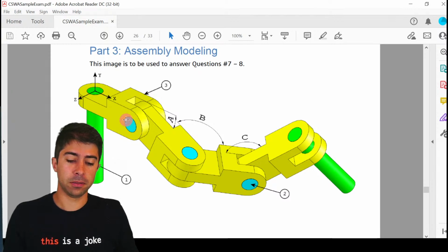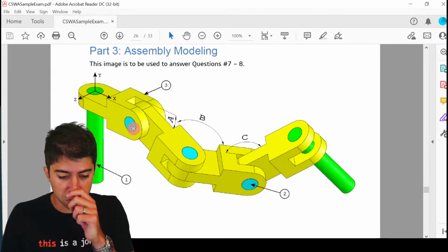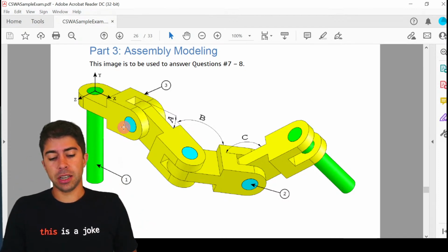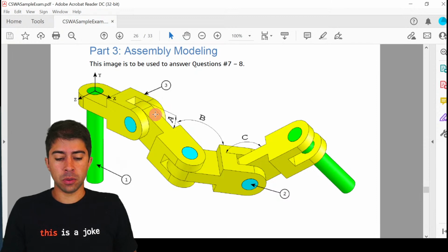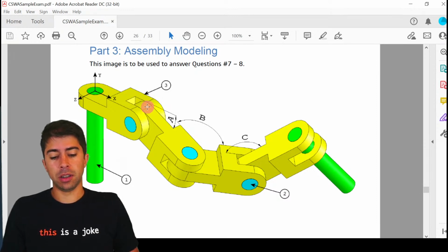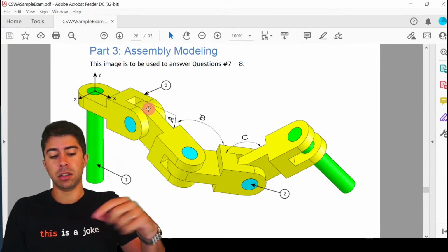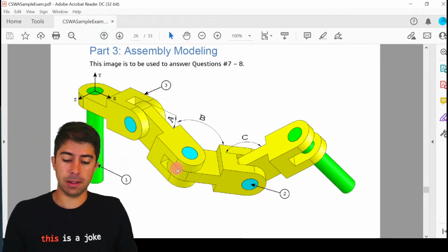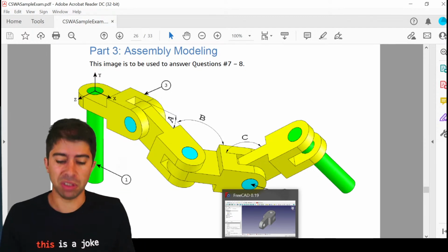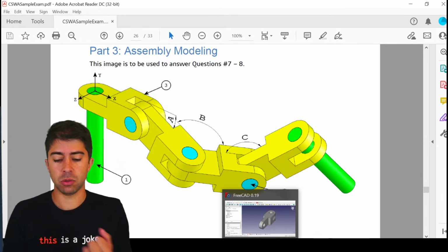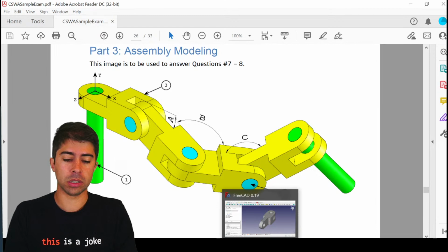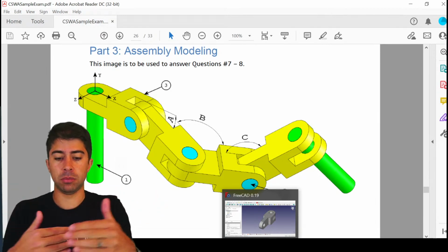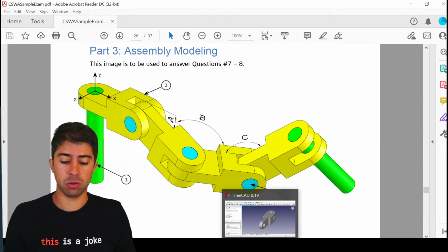side here as well. Also, with the short pin, we've added a local coordinate system right in the middle, and you can see here it connects with the short pin. So we might actually want to put another local coordinate system in the middle of the one hole on the one side, so those two can mate correctly as well. So those are things you need to think about when using the assembly workbench. Where do I need those local coordinate systems? When I actually put everything together, I can then use them to quickly mate all the parts together.